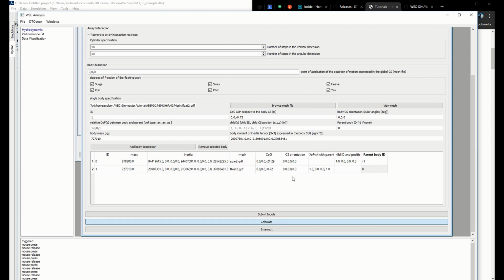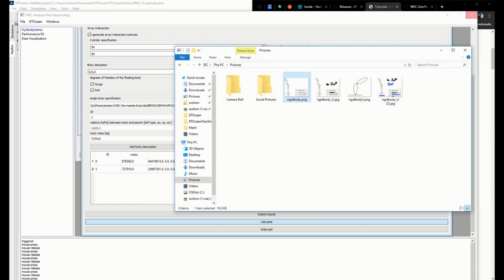At this point, this window freezes and the interrupt key will not work. And this sort of wheel comes up anytime you're hovering over this page. I want to mention that the current run, as I have set it up, takes about 3 days to complete. If you want a simulation to complete quicker, reduce the number of frequency bins that are being analyzed down to 100 or less.